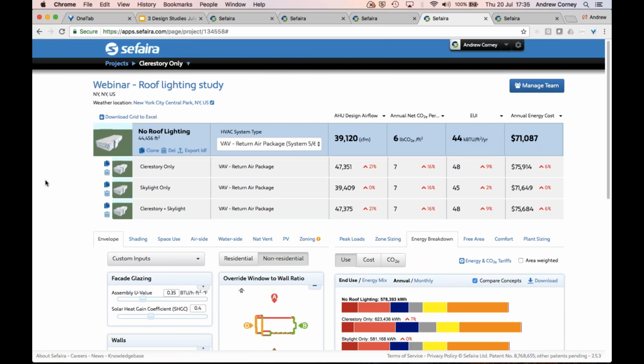And I did a couple of things after the models were uploaded into this project. When you upload a form into a project, you can add it to an existing project. So each of these different buildings, although they look the same, are each of the different options that are described here. We uploaded the different forms into the same project, and so now I can compare each of those different forms very easily to see how the design's affecting energy as well.